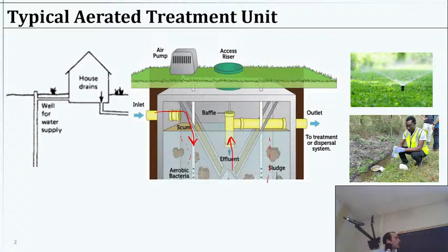We'll take a look at another reactor scheme, but this one's pretty typical of what we would see in Louisiana. We'll notice we've got gravity doing that particle sedimentation again for us. We've got aeration to promote the biological growth, and the biology is really what's driving the waste consumption and transformation. Ultimately, we'll get solids and we'll have to pump those.